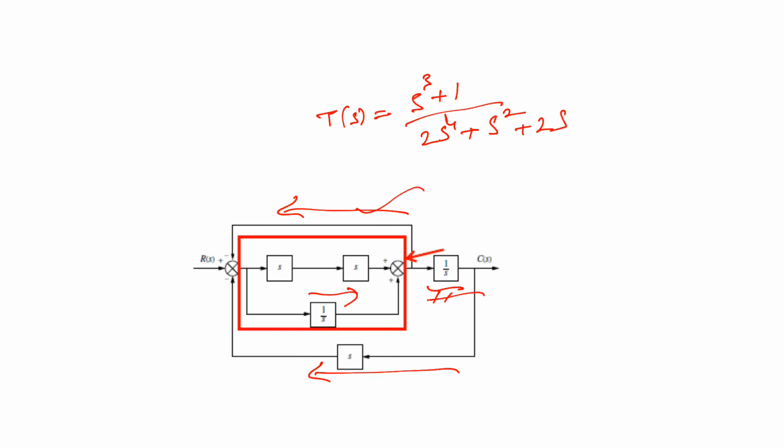So in this we have examined the equivalence of several block diagram configurations containing signal systems, summing junctions and pick-off points, and the configurations were the cascade, parallel and feedback forms. And during block diagram reduction, we attempt to produce easily recognized forms and then reduce the block diagram to a single transfer function. And now in the next section we will examine some applications of this block diagram reduction. Thank you very much.